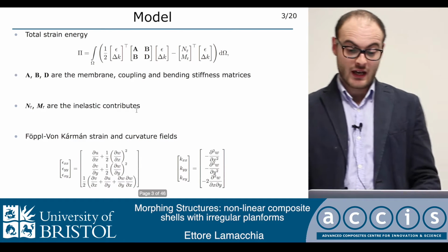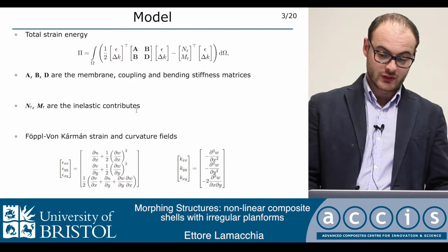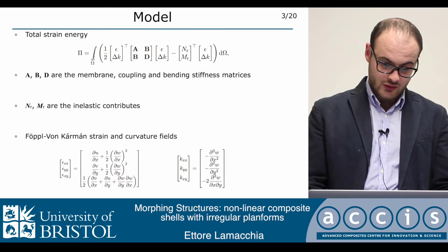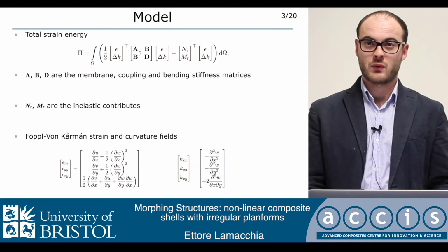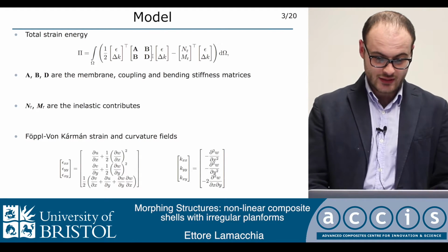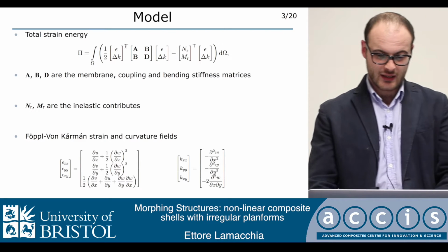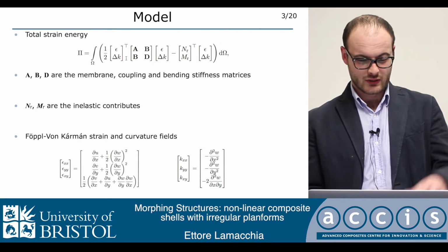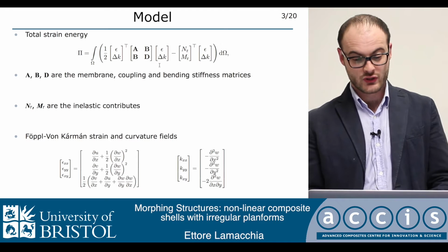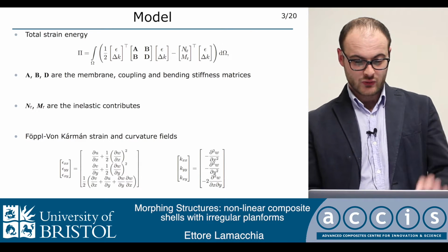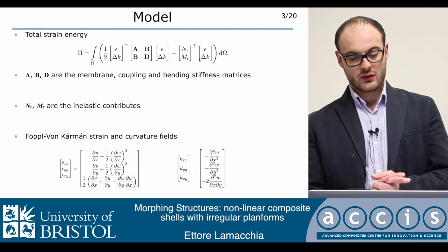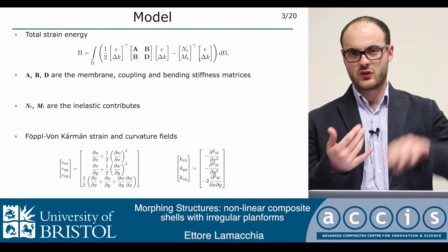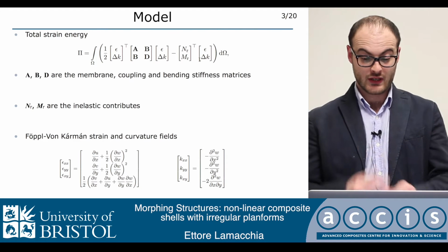And to do that, I developed a semi-analytical model, writing the total strain energy as we see in this equation, using the classical laminate analysis and linking in a linear fashion the in-plane strains and the curvatures. And here we can see the contributions also of any inelastic field. It can be temperature, it can be moisture, it can be piezoelectric.